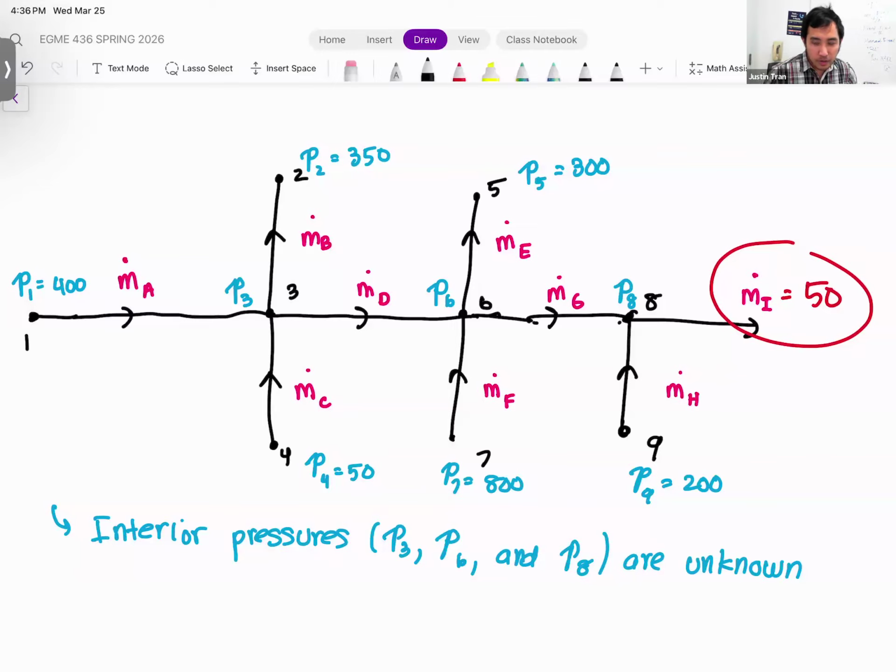All right, so there's a lot going on, so I'll give you guys a second to make sure you write down all the numbers there. But as you're writing it down, we've basically set up a system where we can apply our SIMPLE algorithm. Because remember, one thing I forgot to mention today, one of the requirements for SIMPLE is that we have a staggered velocity and pressure. We have that here, right?